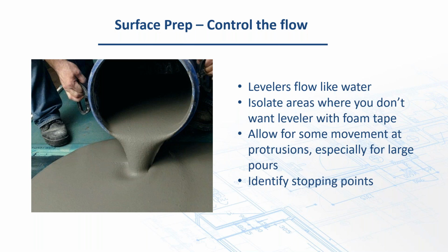Primers do need to cure. If you pour over a primer where the top surface just feels dry, but it's not completely dry all the way down, levelers may tear it off. So you want to make sure that you've got it completely set. Follow the directions. We've got one for non-porous surfaces. It says it needs to cure a minimum of 5 hours in ideal weather conditions. If it's cold out, it may take longer. Almost all these materials are going to take longer to cure if it's cold out. So pay attention to temperatures, high humidity, things like that, and how it may affect your primers. Make sure they're good and set.